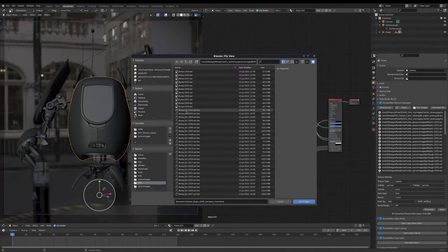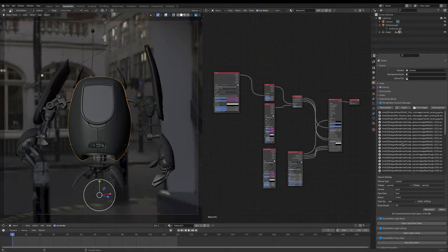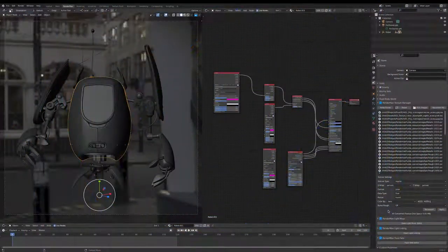You can see that because it adds this underscore B2R. The way you do that is you select the bump maps within this list here, and then you change this bump rough parameter. So you then specify whether the input EXR was a bump map or whether it was a normal map. And then the texture manager will go ahead and convert all of your bump maps to this special bump to roughness map.